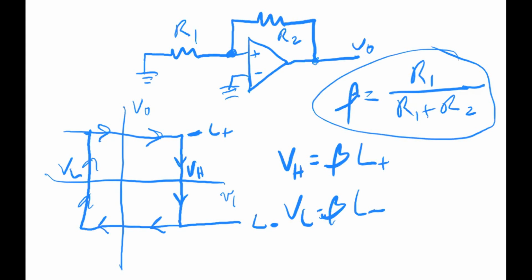So what that means is that when this is in the positive trajectory, at some point the voltage is going to get above the threshold and it's going to switch. But how wide this is is defined by the beta. So the vertical is set by the power supply, but the hysteresis really is set by the beta, the ratio of the, well, it's just a resistor divider between these two.